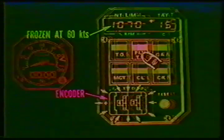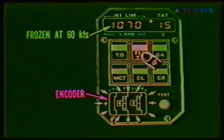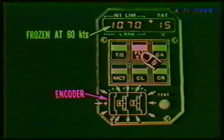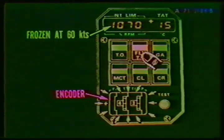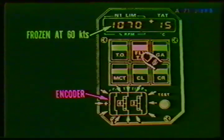A few words about the different modes. Takeoff, or TO mode. During takeoff, the N1 limit value increases according to the speed and is frozen after 60 knots. This value must not be exceeded. Note that the N1 limit value should never exceed 120%.